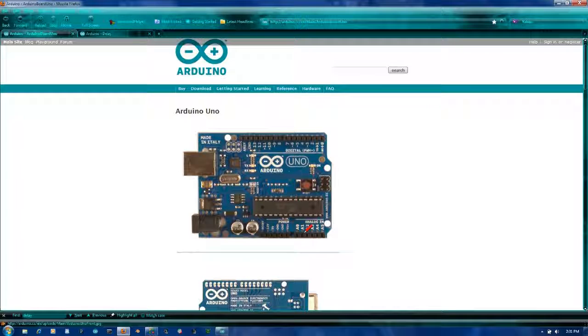Okay, so down here we have our analog pins. See with the A's? We have A5, so 0 through 5. So we actually have 6 analog pins that we can use for sensors here. We also have VIN, which is volt in. We're not going to be dealing with that right now. We have 2 grounds. Then we have 5 volts, we have 3.3 volts, and we have a reset. So what we're going to be dealing with today is this 5 volts and a ground.